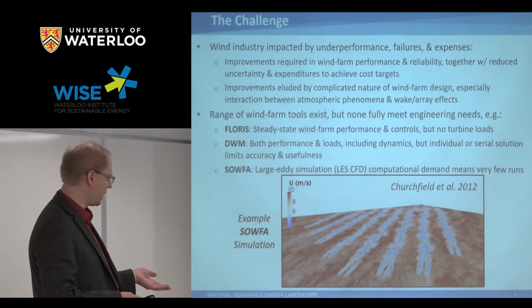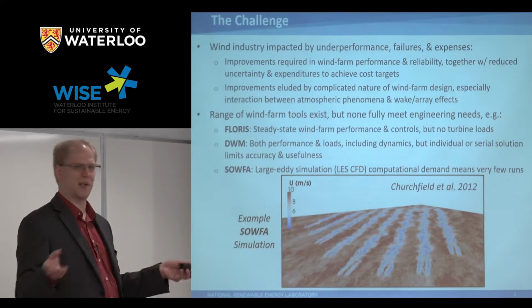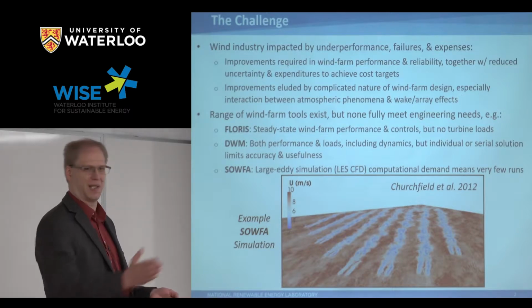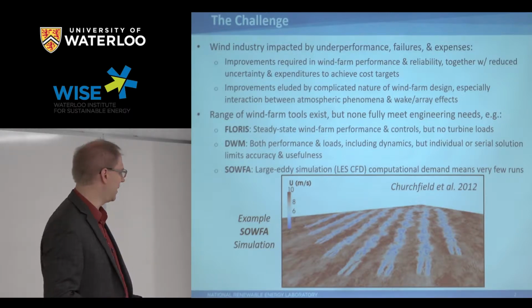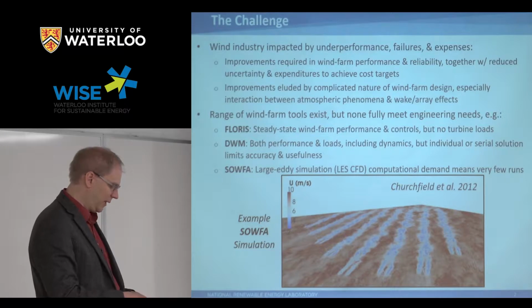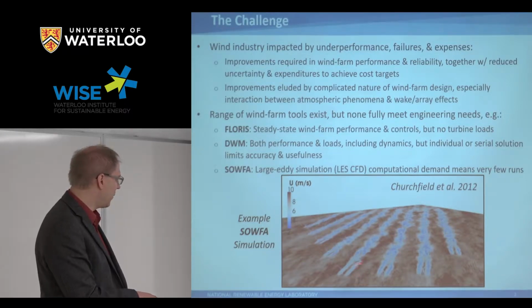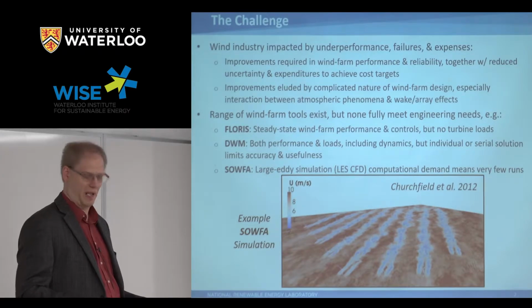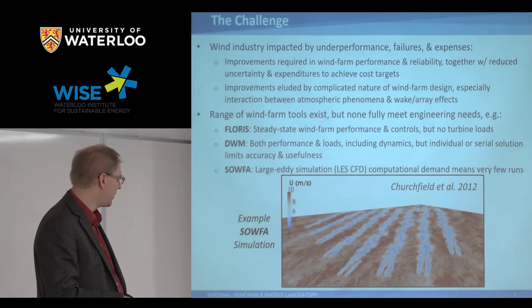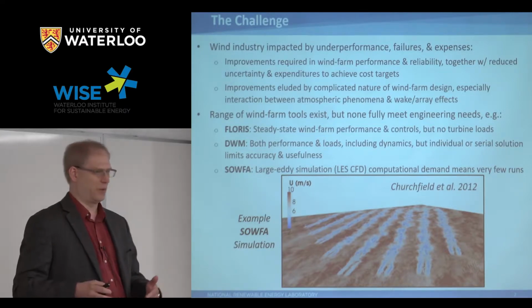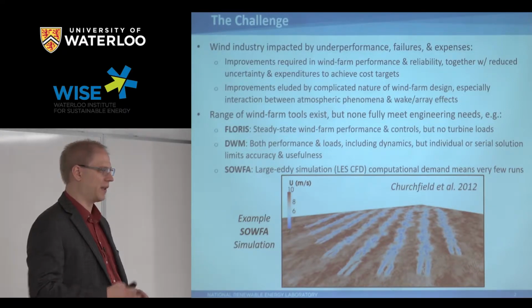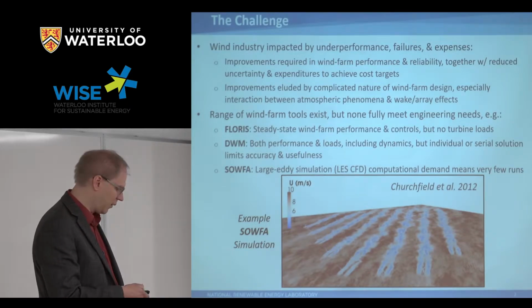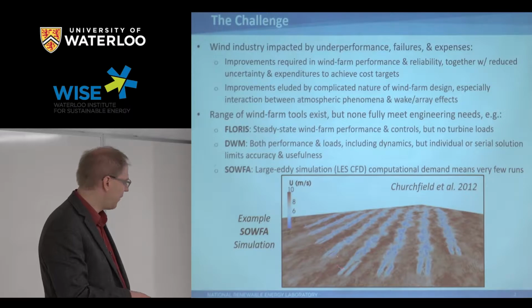One of the novel strategies we're looking at, which I'll talk about briefly, is called wake steering. Normally you want to always yaw the turbine directly in line with the wind to maximize the energy capture. But when you do that, it creates a large wake behind the turbine, and so the next turbine behind it gets much less energy than the free stream turbines. So what happens if we simply yaw this turbine? When you yaw, you have a skewed flow. The thrust is pushing the wake in the opposite direction that the rotor's pointing, and you can then basically skew that flow around the turbine.